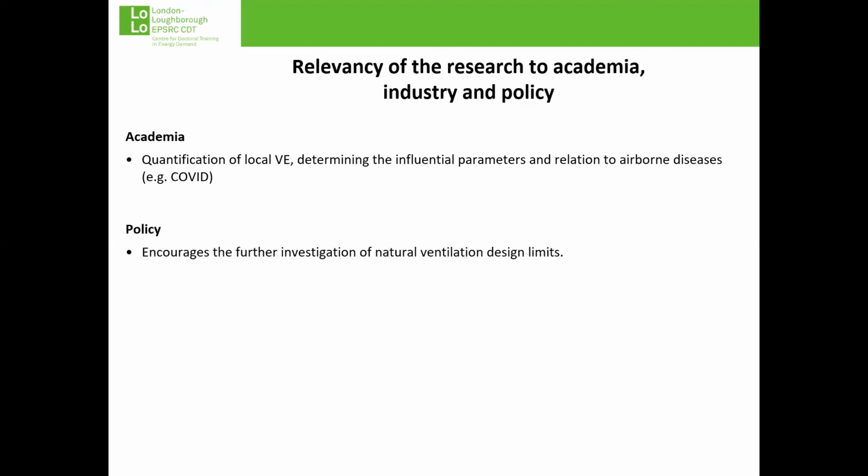In terms of relation to the policy, based on the evidence of this research, the current design policy might consider re-examining the room depth limitation in NV design to allow more flexibility in the design of naturally ventilated spaces. Another point to take home from this research for ventilation designers and architects is to encourage the use of NV even further, given the robustness of this system at providing a high ventilation effectiveness regardless of the prevailing external conditions.